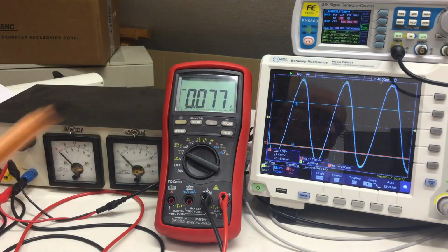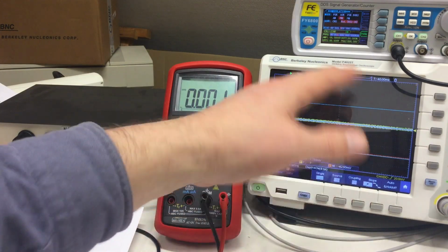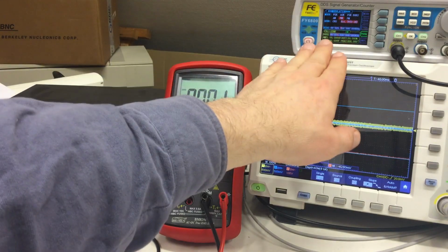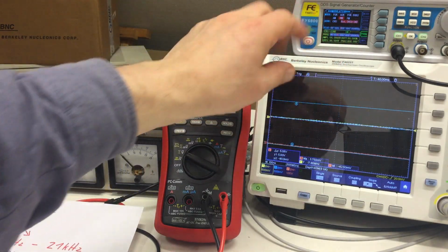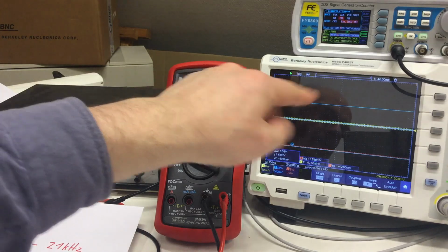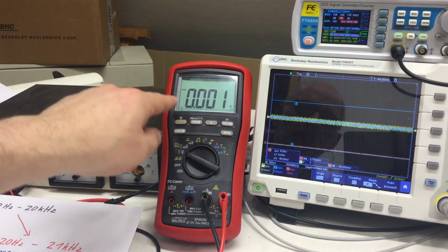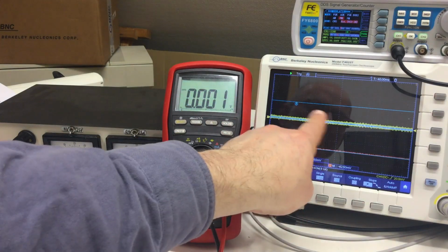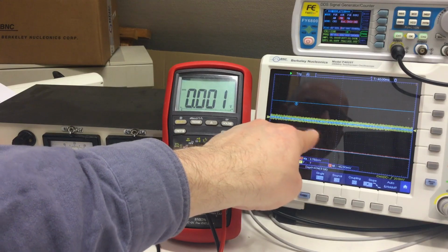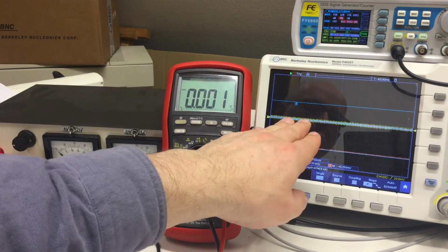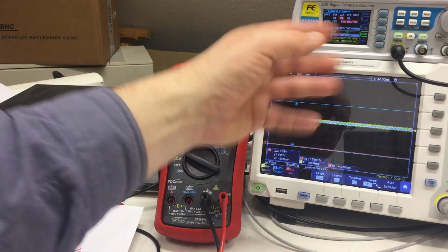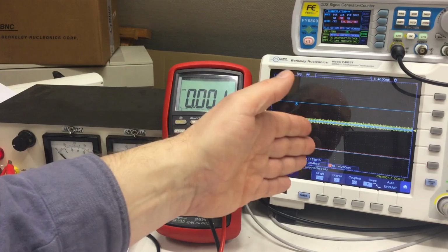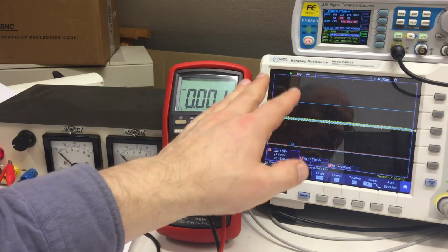Let me do a little number crunching. Okay, I tried using the data I took to fine-tune the frequency modulation settings here, so we get a nice 20 Hertz to at least 20 kilohertz between 0 or a little bit negative and 5 volts, but you will end up totally screwing up the output of the generator. So I will take the initial settings, which should work, and we'll just cut it short at 19 kilohertz at the top, and yeah.